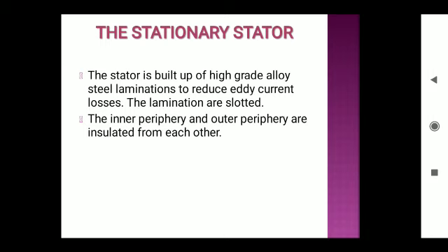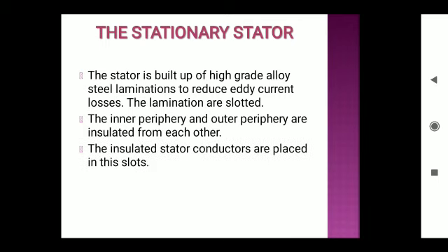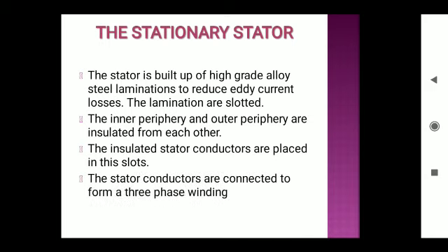The inner periphery and the outer periphery are insulated from each other, and the insulated stator conductors are placed in this slot. The stator conductors are connected to form a three-phase winding. It may be star connected or delta connected winding.